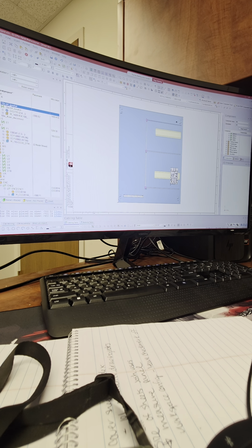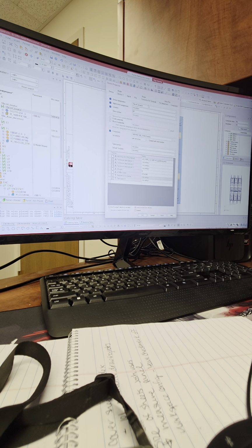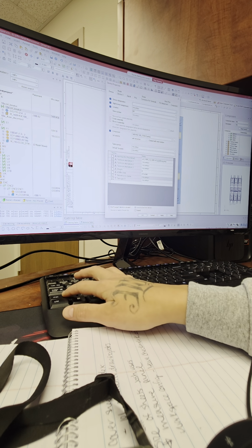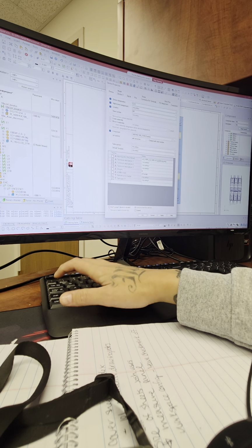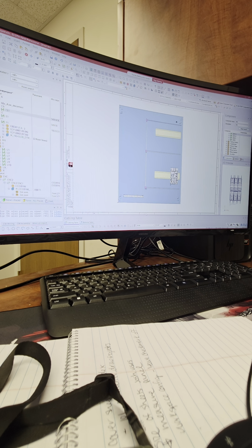So right click on this green item. I think I just realized what you were saying. Right click on device properties. Click on the devices tab. That's where everything kind of starts. So normally in projects this will be referred to like a CB1, circuit breaker 1, from a reference perspective. All references are capital. So this will be the normal, standardized, project usable name, if you will. So click apply and OK. That will fix that, now that I know what you meant.